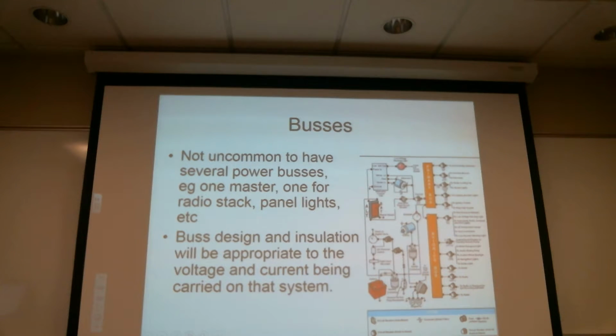Another strategy for bus design, which I don't tend to see too much in aviation, but we do it in ground-based stuff all the time, is called the ring bus. So for example, all the buildings and structure in this college, all the power comes from a big ring. That way, if somebody nails one corner of the ring, you can isolate that out and you have the other pathway to route power out to all the different buildings. That creates a level of redundancy.